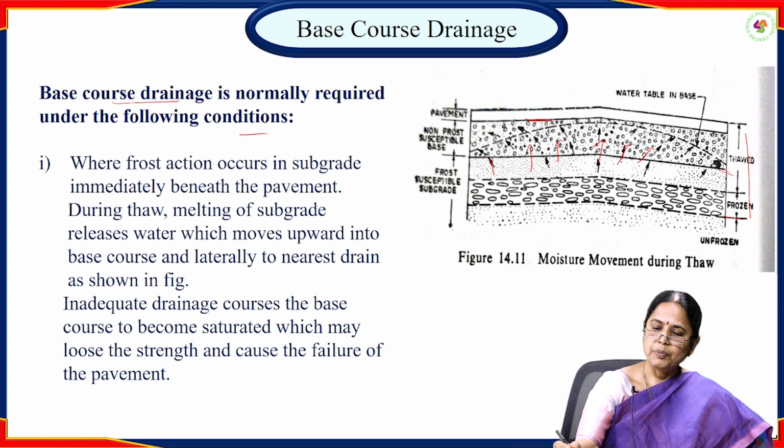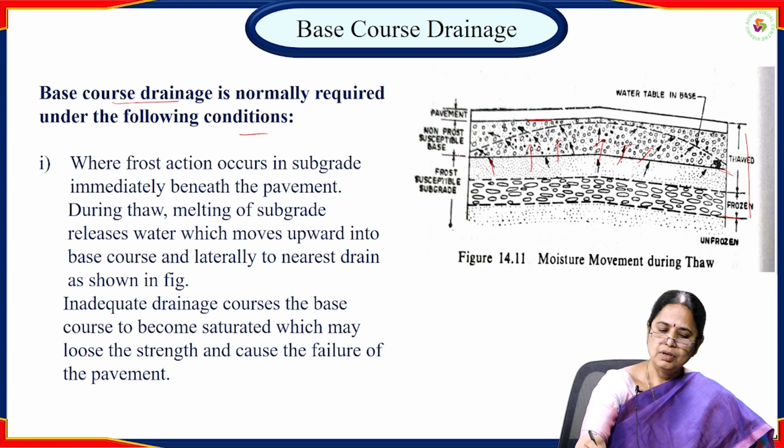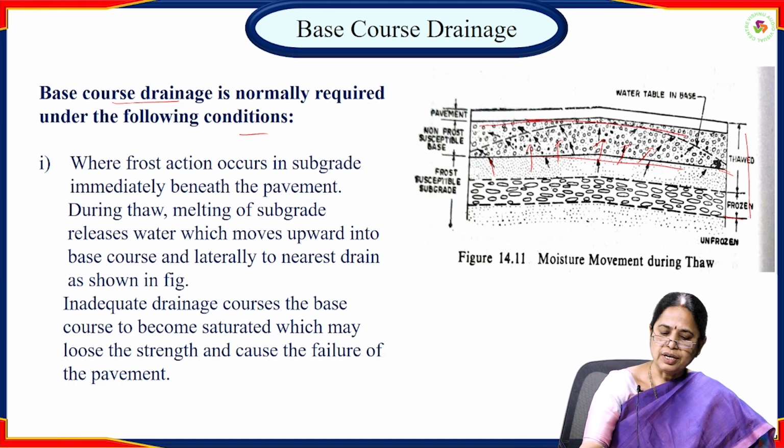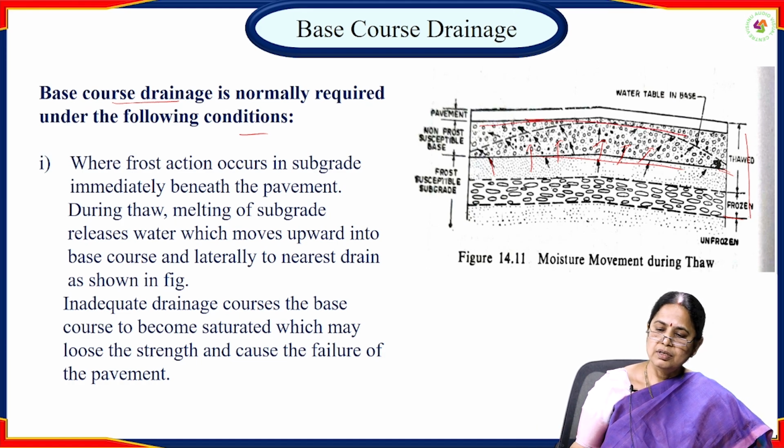If you provide inadequate drainage, then the base course becomes saturated, loses its strength and causes failure of the structure.